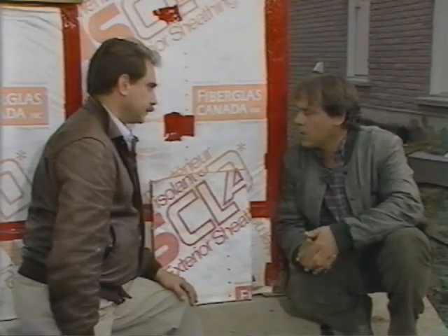Always. Well, gee, we've covered air and vapor barriers, and also air-vapor barriers, and the 1/3, 2/3 rule, which I have a feeling is going to keep coming back on me. Am I right? It's going to come back a lot. The argument here is that if you understand the building science issues behind the selection of the materials and their use, you can buy the right thing and do the job properly in the field.